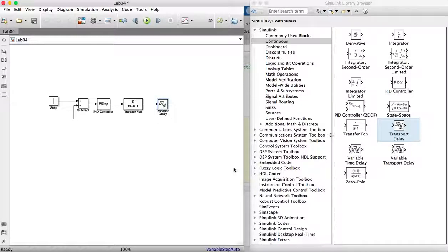Let's go extract the information from our simulation using sink blocks, so we may use it in our lab analysis. This is where the sink category comes into play. A sink is any tool that allows data extraction from a Simulink system, either to work with within MATLAB or to display it to the user in some meaningful way.